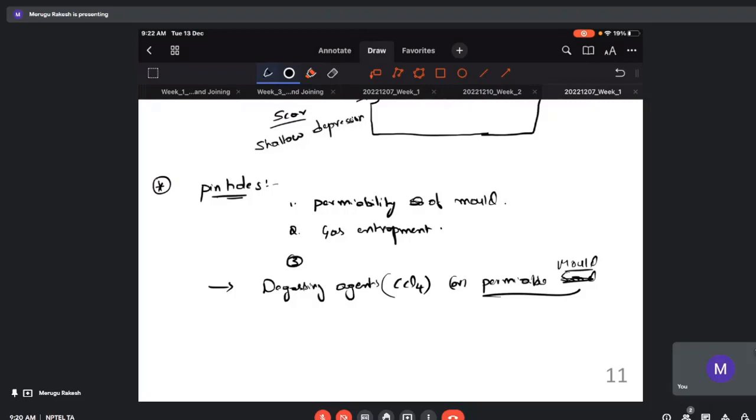This gas presence cannot be completely removed. So we will have a limit in PPM for hydrogen for industrial standards. It should be below that point in order to accept those castings.